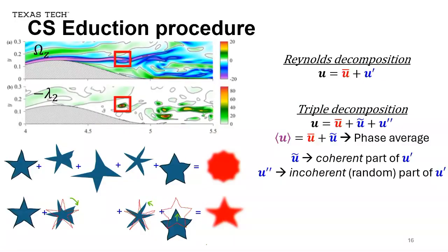So in this process, once you identify based on some criteria, in this case, we are using the vorticity of the shear layer, peaks of vorticity together with the lambda 2 to have some confirmation that this is a vortical structure, and the vorticity to only capture those structures that are more aligned in the spanwise direction.